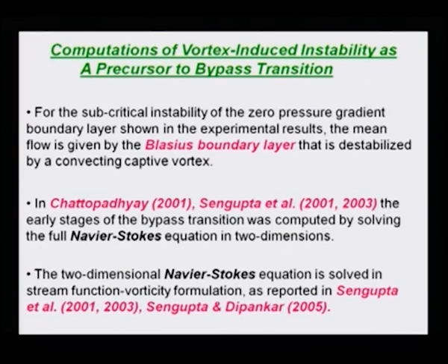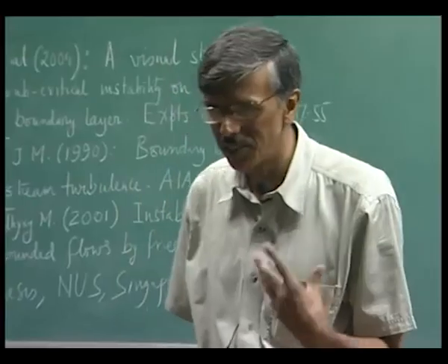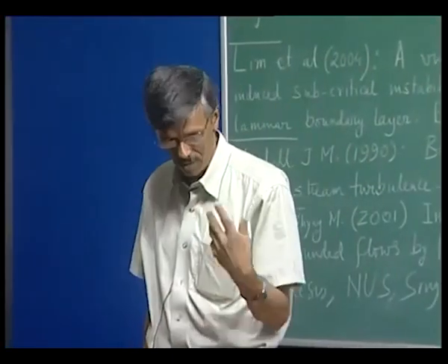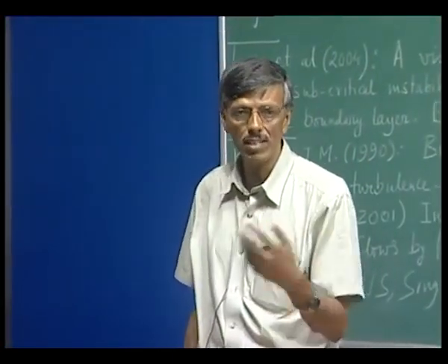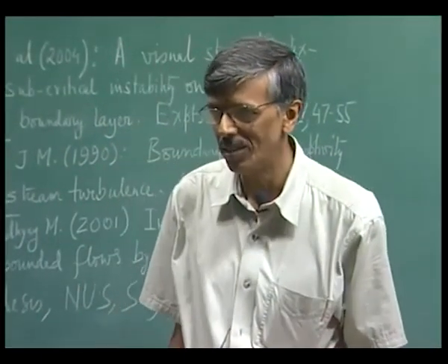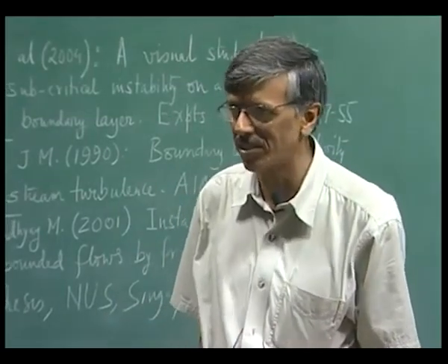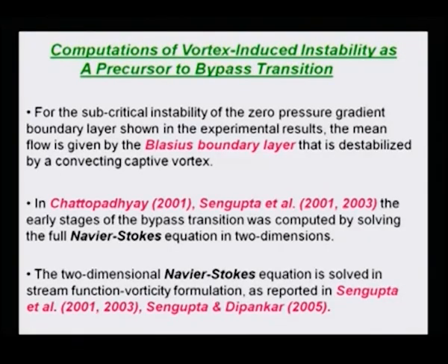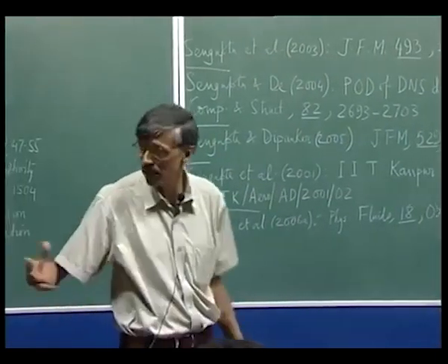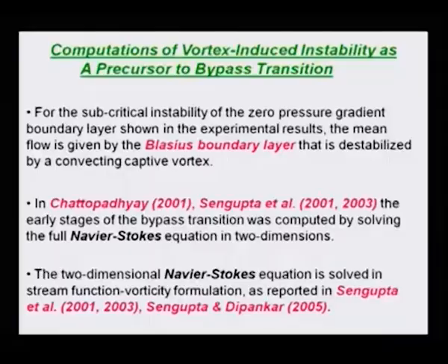Okay. And what you do is take up the Navier-Stokes equation in stream function vorticity formulation, and this you do basically for accuracy's sake, because the existence of psi, the stream function, would ensure mass conservation in a numerical sense, and basically fluid mechanics is all about vorticity dynamics. So, there is nothing better than working with the vorticity itself. So, this formulation is always recommended. These are the references that you can see, and in this we have defined all these methodologies that is written there.